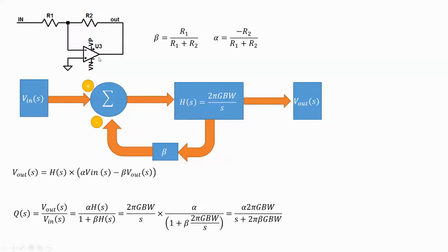Now what about for the inverting? Well, you can again do this in the nodal method, and it might be better this way. But you might be a little bit confused when you're trying to use the system approach, because while you can see that there's feedback from here to here, rather than this being ground, you have Vin.